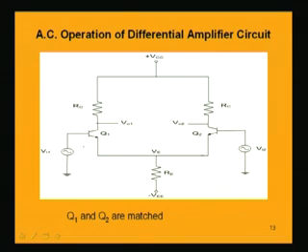As these two transistors are perfectly matched, that is the prime condition to be satisfied. That is why we will have the same beta value for the two transistors. As well, the emitter resistance Re of the transistor, that is the resistance in the emitter-base forward biased junction, will have the same value in both cases. So, if we analyze this circuit under AC, we will have to draw the AC equivalent circuit for the whole amplifier, and that requires drawing the AC equivalent circuit.